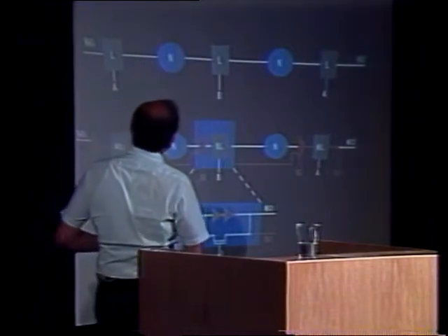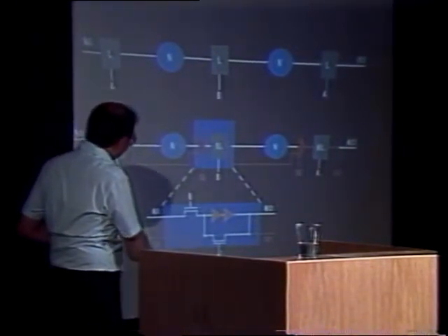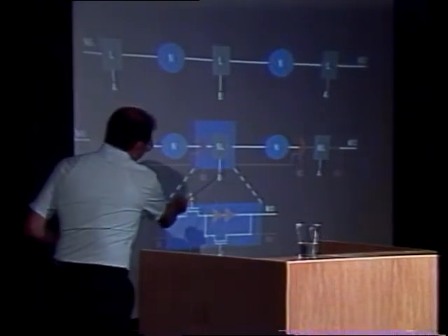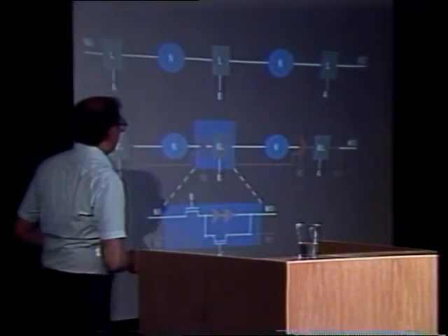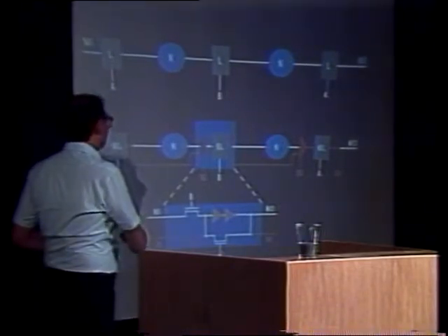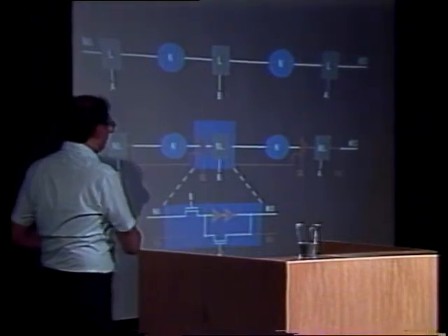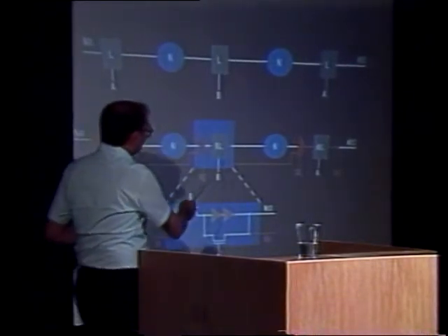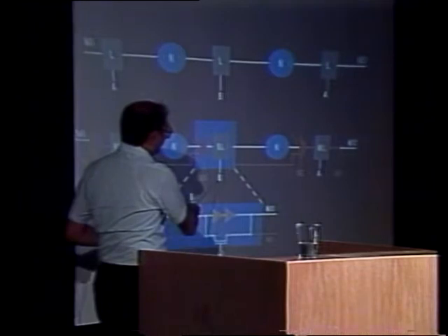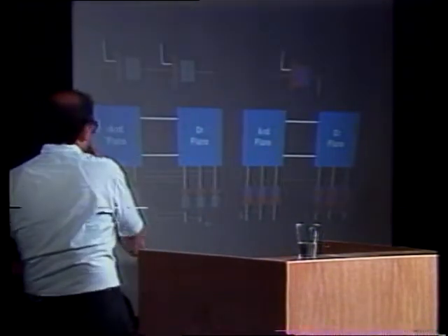What I have shown is only one latch clocked by A over here and another latch over there. But usually these latches occur in clusters. You may have a register here clocked by phase A and another cluster over here clocked by clock B. For example, take this PLA.